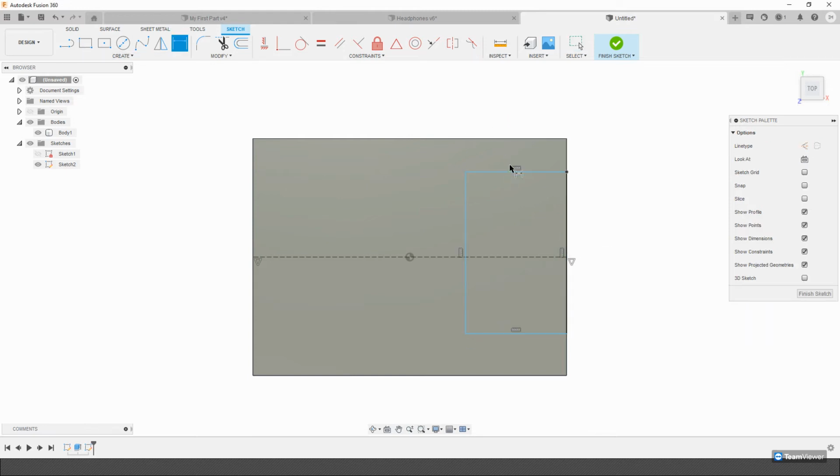So parametric modeling, meaning that I can do this. I can simply draw my shape very freely, rough-handed, just eyeballing it. And let's say 50. And come in later and define my dimensions. So I'll say 100 by 50. Now, of course, because I've only defined those two things, those stay locked, they're constrained. It's parametric, remember? And I just need to make sure that it's in the center.